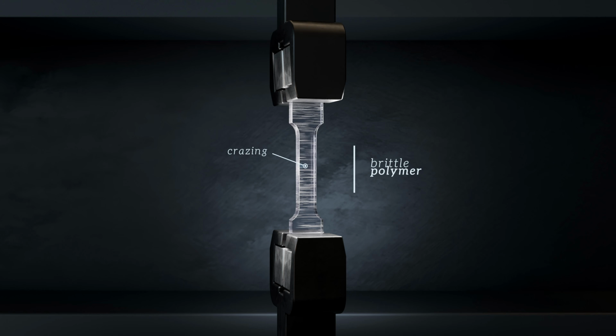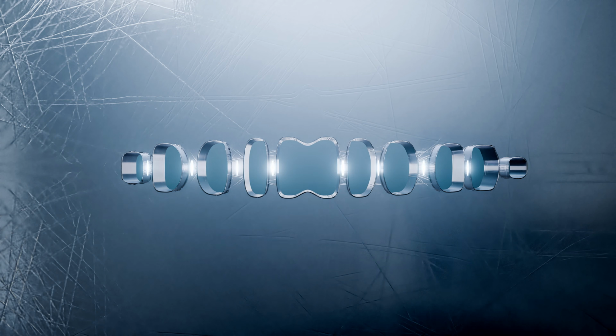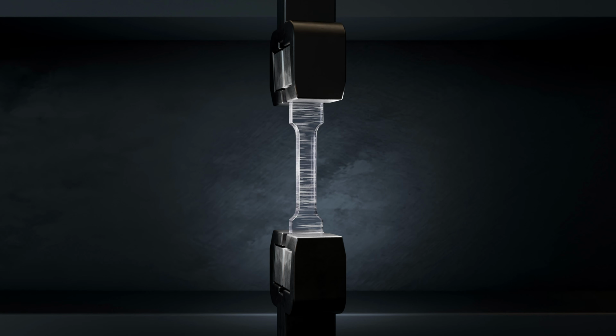These features are tiny voids within the polymer, but unlike cracks, the voids are bridged by fibrils of polymer material. These fibrils are load-bearing, and they absorb energy, which delays crack formation and propagation. If the stress continues to increase, these crazes can grow into full cracks, leading to failure. It's usually difficult to visually identify the onset of brittle failure, because it happens so suddenly. But crazing can give an early indication that catastrophic failure may be imminent.